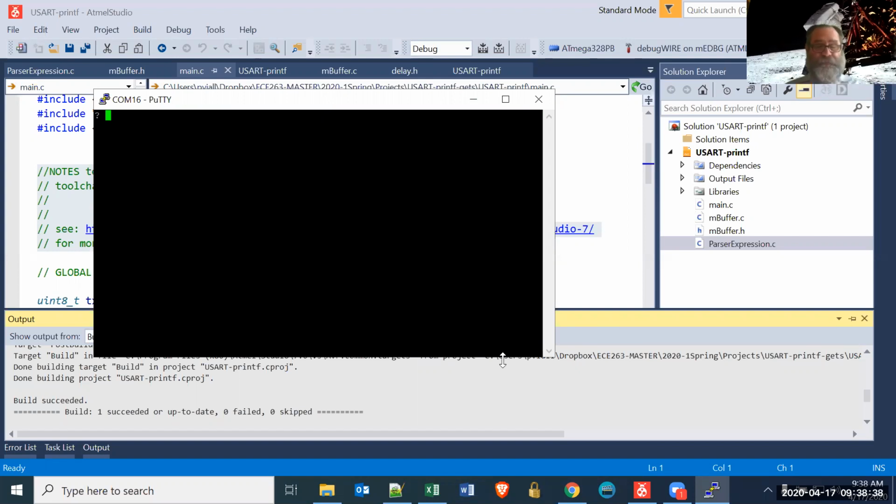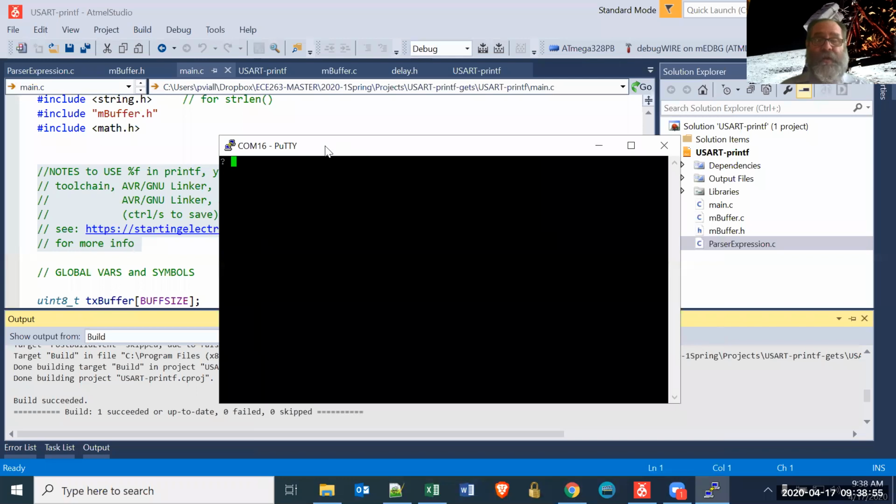Okay. Things to check if that happens, so you don't even get anything out: there is no magic way to do this. You'd need to set a breakpoint, probably at the put character routine. And when you're using debugging, it's probably a good idea to do no optimization. There is a flag supposedly to make debugging great. My experience is that does not make debugging all that great. No optimization is far better. So set no optimization at all.